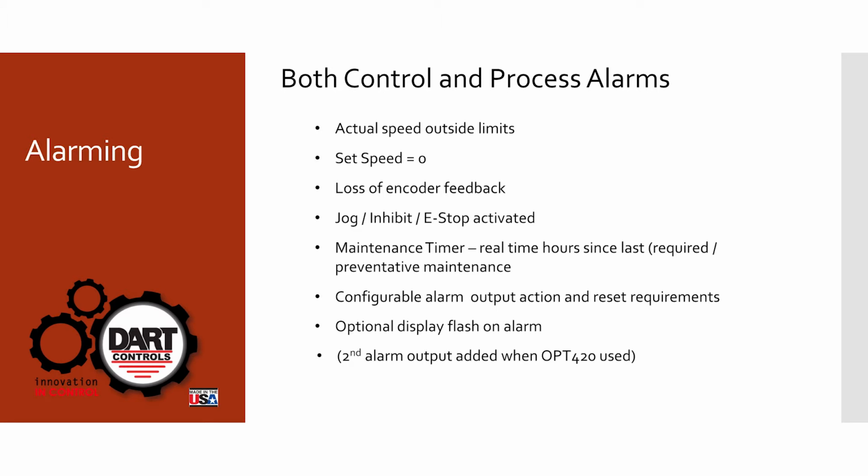All alarms are routed to a Form C relay, and you can actually logically AND or OR multiple alarms to use the same relay output. So the ASP family is a very handy, very valuable accessory to any drive. We have many applications where we've replaced PLC and HMI based systems costing thousands of dollars with an ASP device and have been very successful.